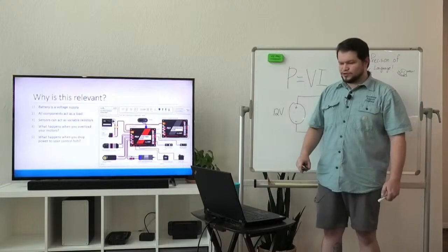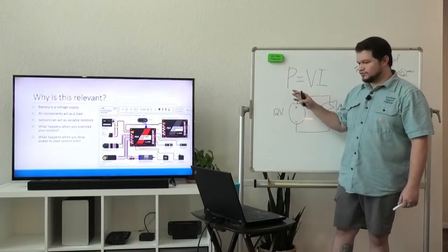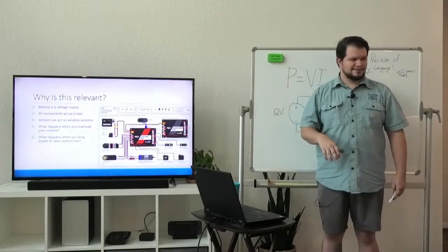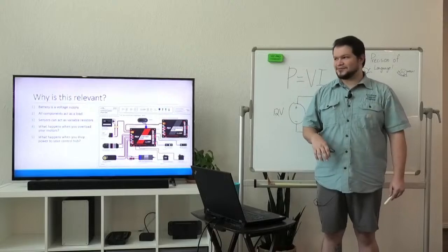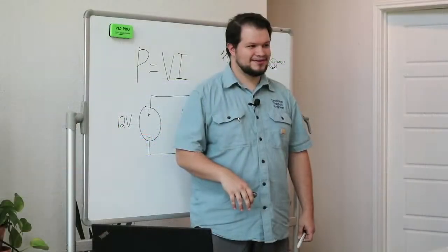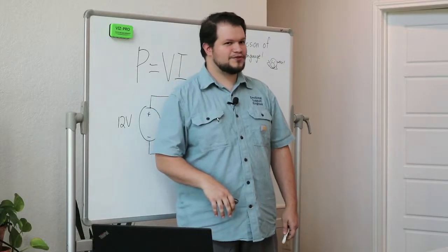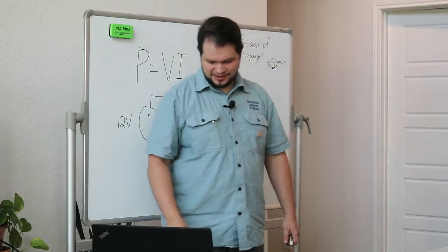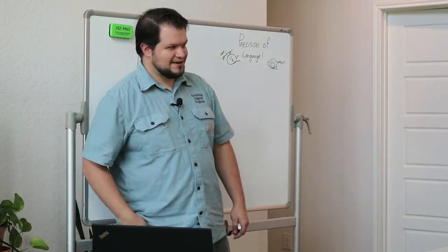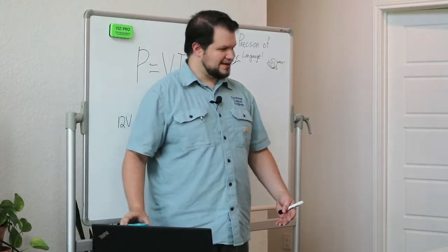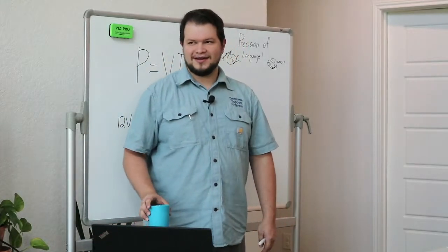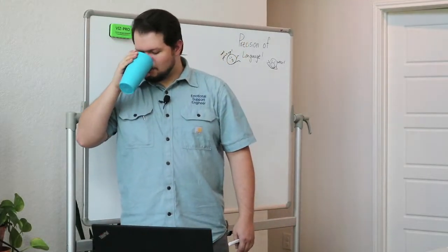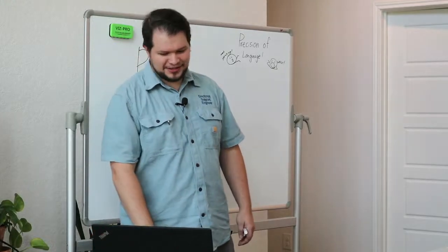We talked about what happens when you overload your motors in terms of your voltage and current, but what happens when you drop power to your control hub? There's lots of experience in here about what happens when you don't get enough power to your control hub. No, that's if you overload and put too much power. What happens if your battery doesn't supply enough voltage? You tend to disconnect, or sometimes, in a less extreme case, it will flash, and then your IMU will reset, and all of a sudden you'll switch from field-centric drive to robot-centric drive. If you don't know what that means, we'll get into that later today.